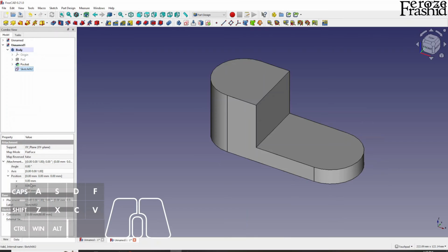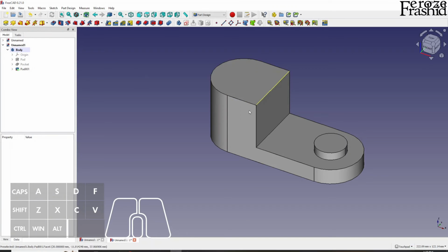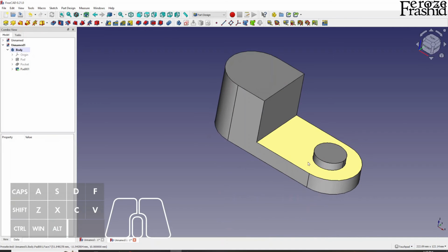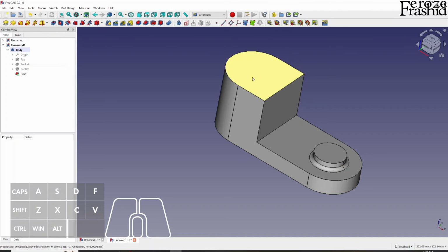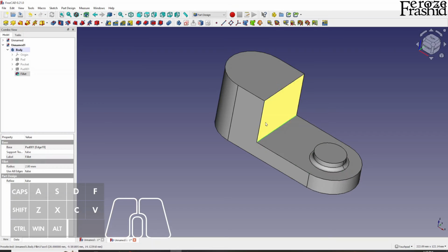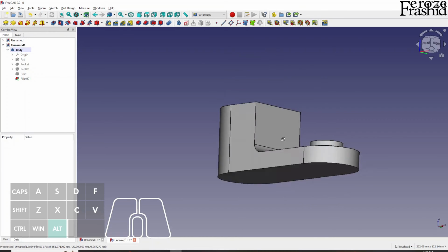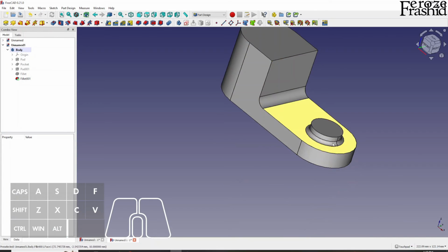This will go 10 millimeter in the Z direction as well and go up by 5 millimeter. So we have the outside shell built. Inside it's solid, no feature added. Let's go ahead and take care of these fillets as well. This is 2 millimeter and this fillet will be 5 millimeter. All right. So this is solid inside and we got the outside features built.